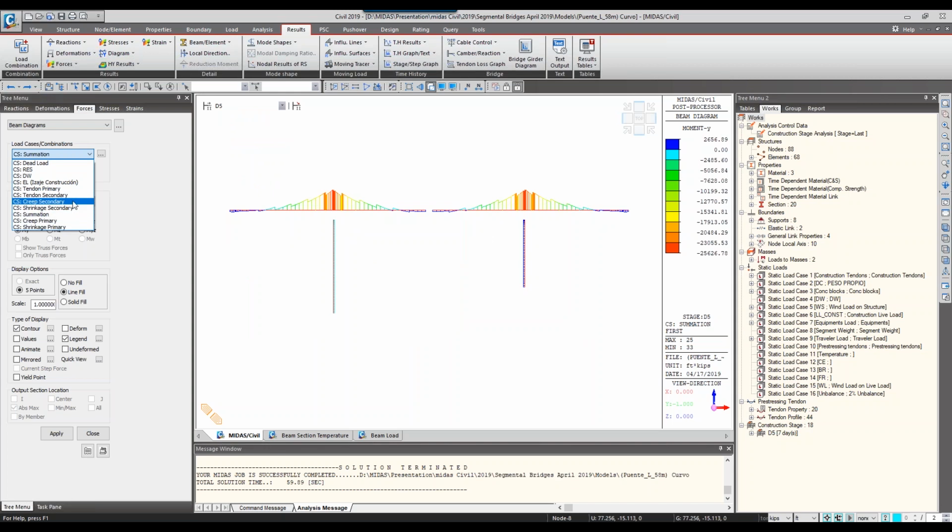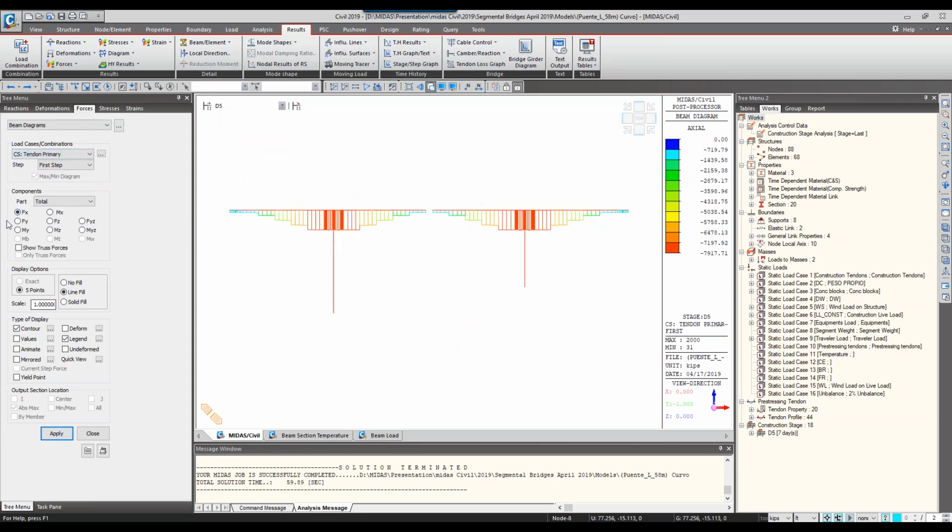We can consider what is the effect due to the tendon primary forces as well as the tendon secondary forces. And here we can check what is the effect of each one of the tensionings, for tables, in table format, right before closing, since this is one of the most critical situations that can happen. These situations need to be considered in great detail, as well as for a particular report.